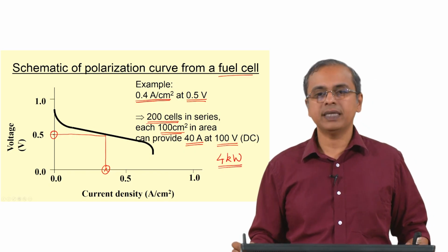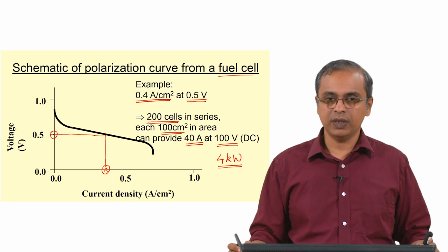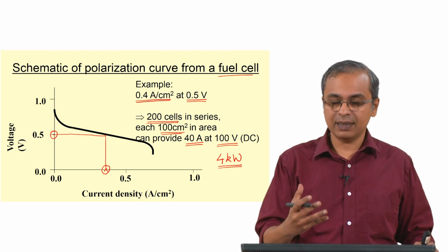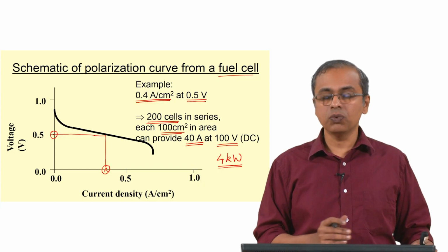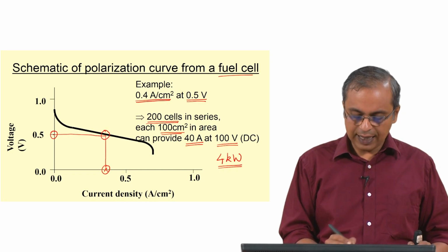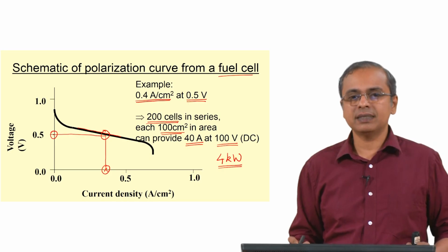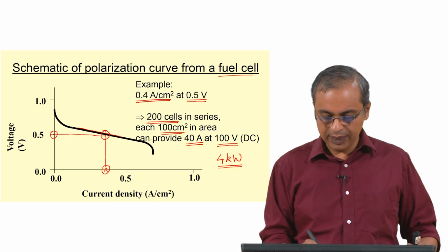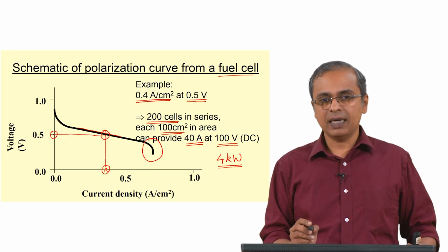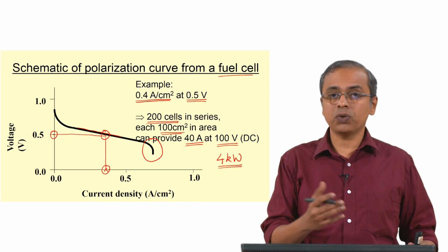of power that is being generated from this unit, and this is the polarization curve corresponding to this unit, and therefore I am able to set this point as the set point for this unit with good confidence that I am operating at a relatively safe area. So please note that right here I am sort of in the middle of this polarization curve. So I am in a fairly safe operating point, as opposed to being down here where I am at a shaky operating point, meaning if the operating point changes marginally, I am not going to see a collapse of the system.